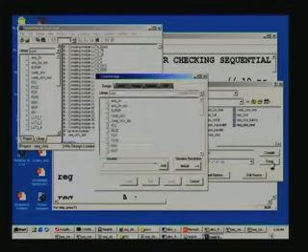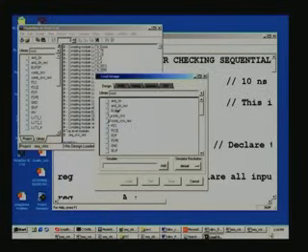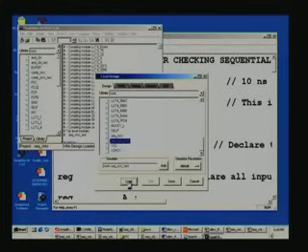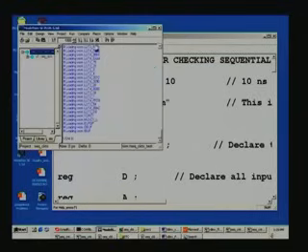We do not need the compile here, so we will remove that, and this is the load file, and once again same buffer, all those primitives it is reporting here. I think towards the end you have sequential circuits underscore test. So, let us load this file. While loading also it has displayed all those primitive cells here, and there are no errors. So, we can conveniently see the waveform now.